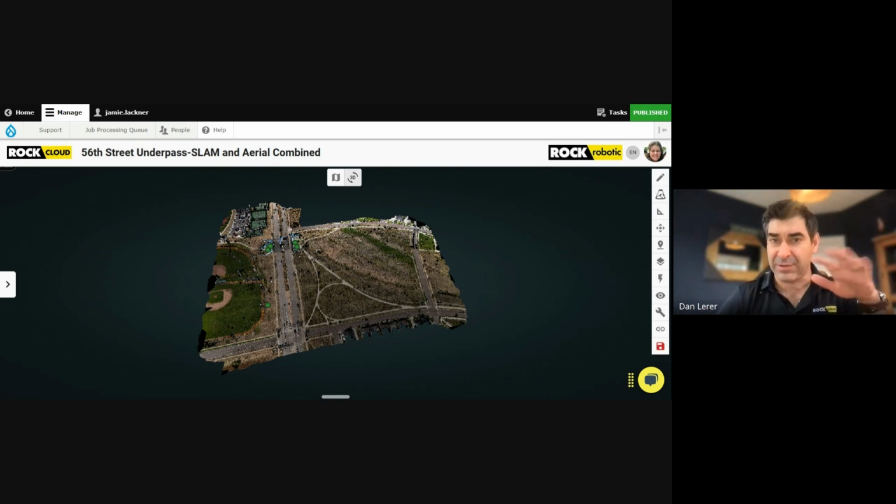We'll take you through the data acquisition and how drone LiDAR data combined with RTK ground control points enables you to have quick and safe collection of millions of survey-grade data points. We'll talk about the data processing, using ROCK Desktop to create the 3D point cloud and the ortho mosaic, and how ROCK Cloud makes it very easy to visualize, share, and align the data. You can also correct your local coordinate system and projections to make sure it's all in the projection that you need it in.